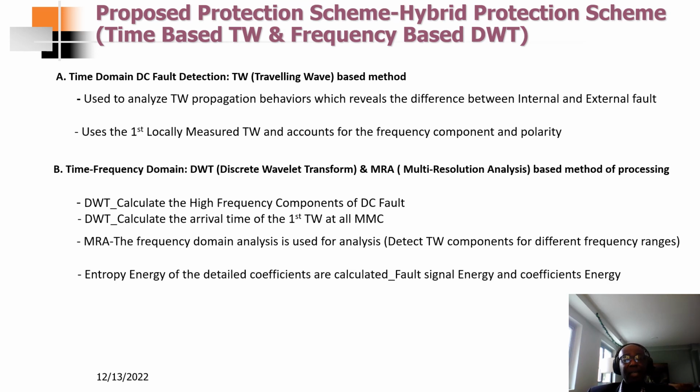Then, again, the entropy of the detailed coefficients, right? Remember, I'm utilizing a discrete wavelet transform and multi-resolution analysis to perform calculation of detailed coefficients, and based on the detailed coefficients, I'll calculate the entropy energy, and that will be the basis of detection of faults.